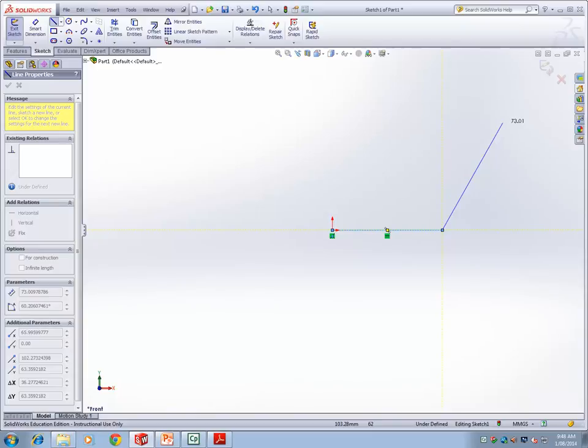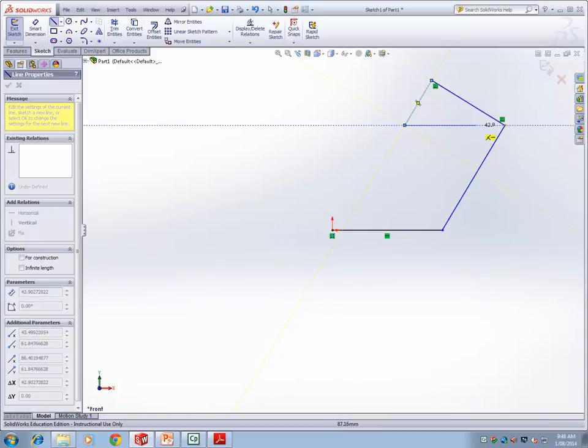Then again you want us to move perpendicular to line 2. You snap somewhere in the model space. Once it is snapped, you want to draw a line parallel to the existing line 2, and we also want to maintain a coincidence relationship. For example, in this case, I want that particular snapping point to be in the same collinear arrangement with this point here. So this is where I'm snapping it parallel, and also it's collinear with the vertex point somewhere here. Once drawn, you can move further to snap it to a coincidence point which is horizontal, then one more vertical line. Once we close this one, you can simply press escape.